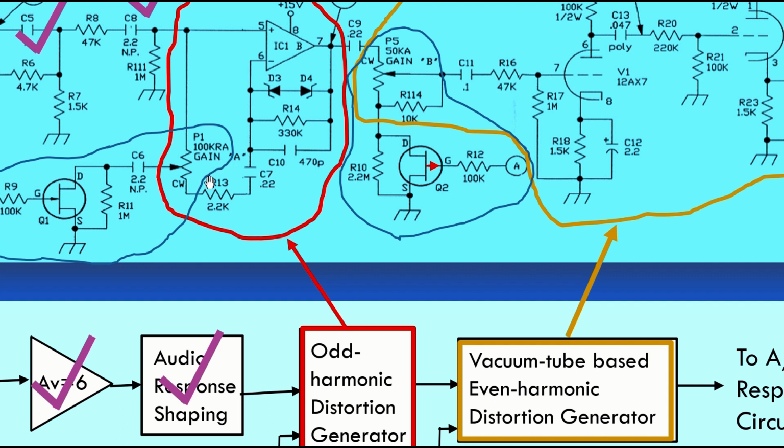But if you're a guitarist, you know that you may not dial that gain all the way back. Sometimes we want a rather harsh sound, a gritty sound, or whatever your favorite adjective is there. So we might run this gain pretty high to make sure this thing does saturate and clip. And that's what these diodes are for as well. And under that situation, we will get what's called odd harmonic distortion. We can actually turn that distortion off with a control on the front panel that will affect what this transistor here is doing, whether or not it's AC grounding this point.